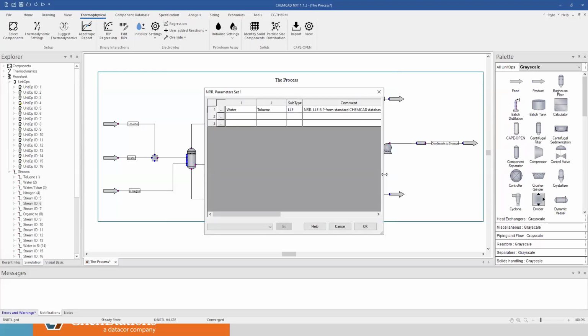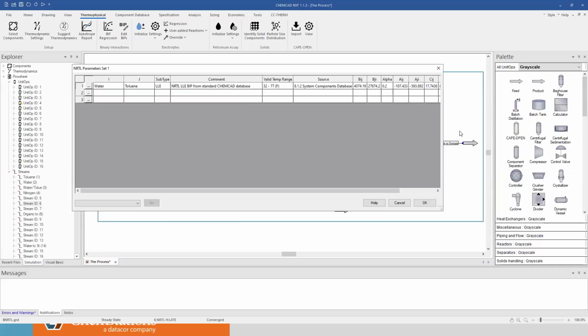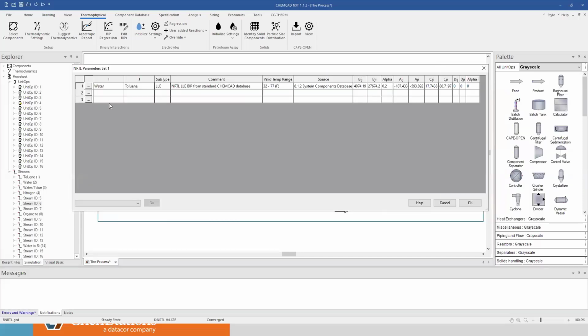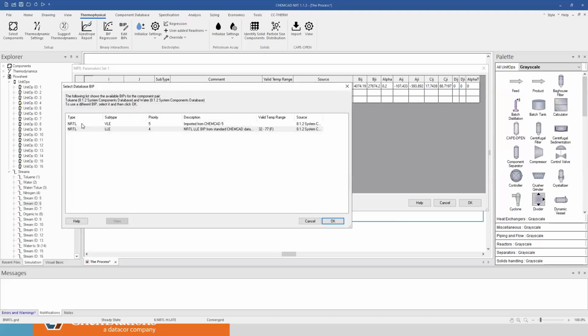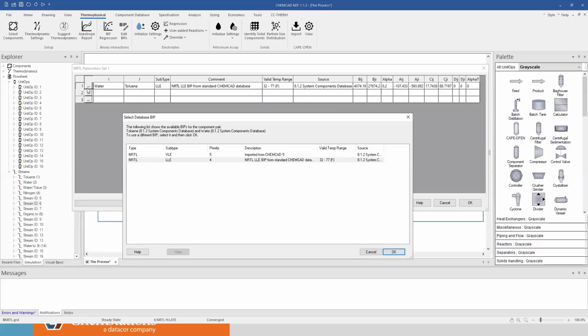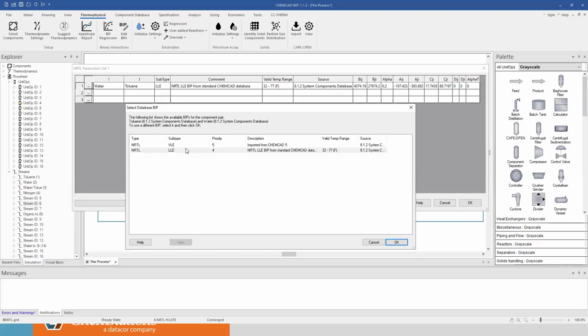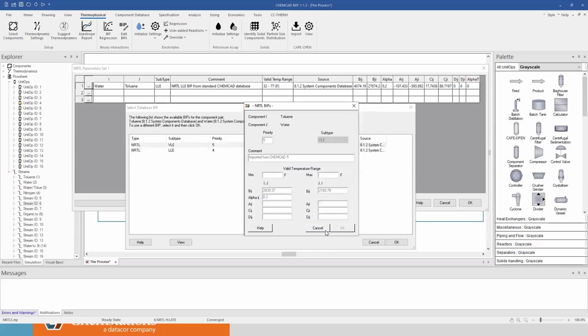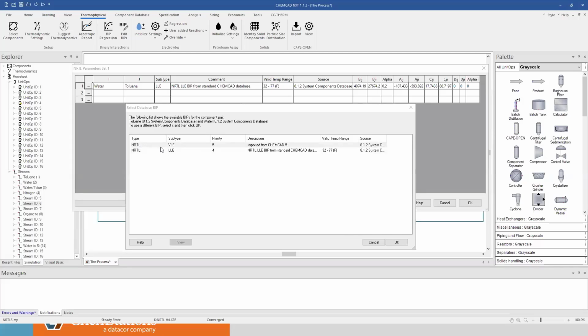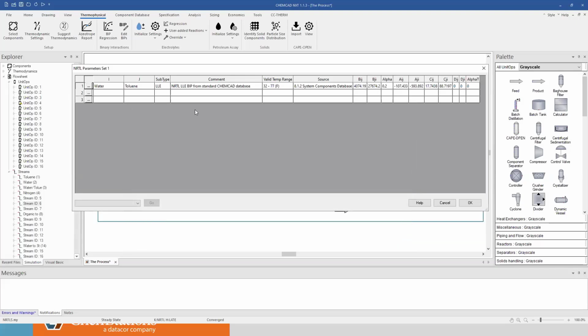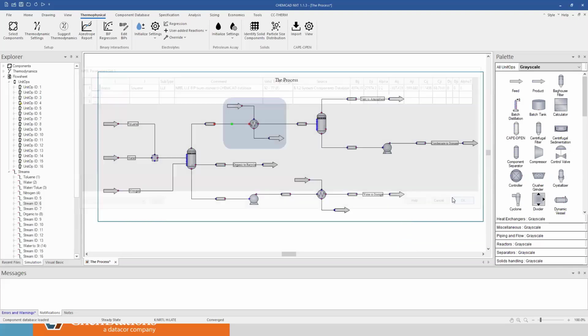it's going to give me the parameters for the system. And as you can see here, this system says liquid liquid equilibrium, but it is because I already chose it. You see, if I click on this little three dots here, it will open up what this system's available BIPs are. And in here, normally it will select this one, okay? But because I know that this system forms two phases, I will select liquid liquid equilibrium. So I say, okay, now my liquid liquid equilibrium is here.